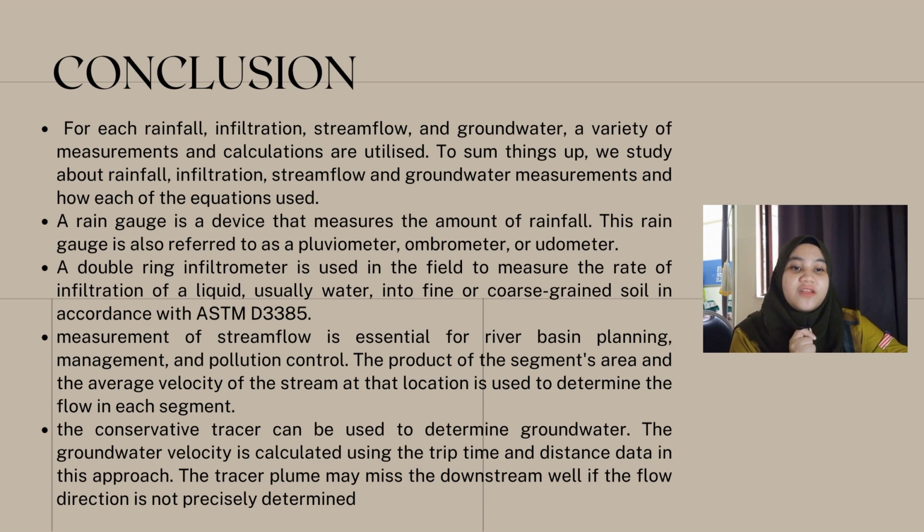The result of the infiltration will be recorded and the Horton equation will undertake calculations based on the results to determine the exact value of water infiltration into the soil. The infiltration capacity versus time curve is used in the traditional Horton equation. The modified equation's simulation performance and uncertainty were compared to those of the original Horton equation to ensure its correctness.